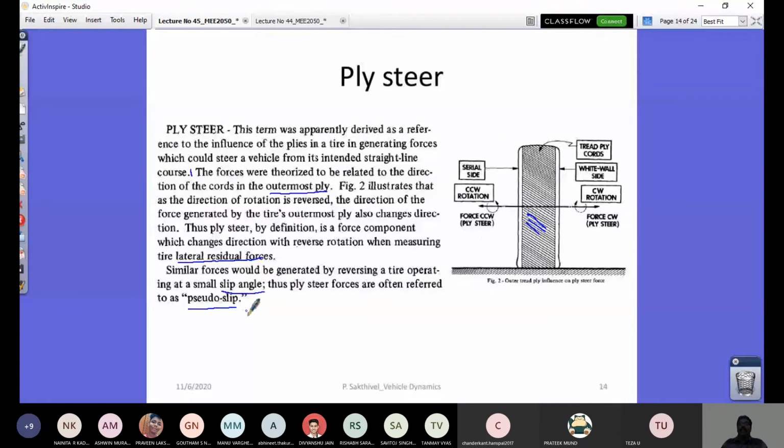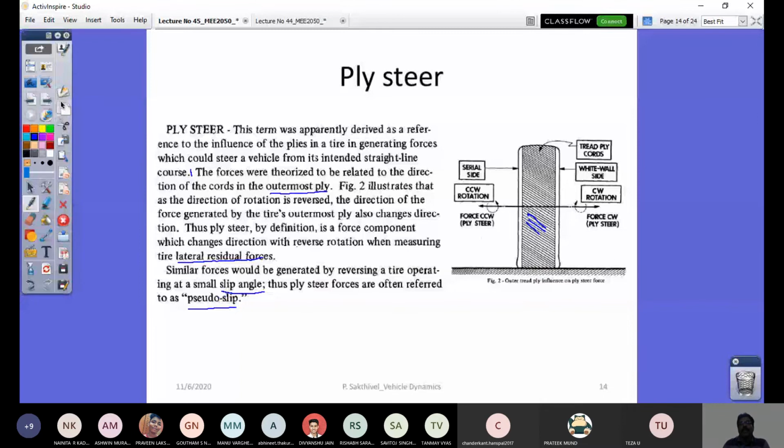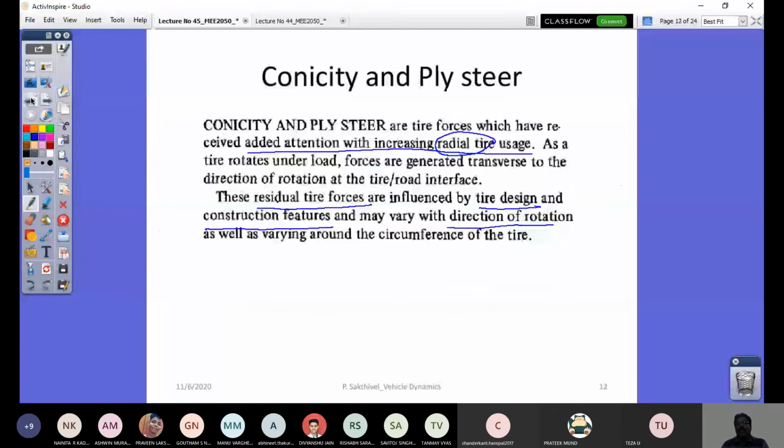When the tire is not actually subjected to a tractive force, that means driving torque or braking torque, that's why it's called a zero slip. So these two effects are to be accounted. That is the reason why in your magic formula model, you see that there is the shift SV and SH. And I think now you understood this formula and this curve.